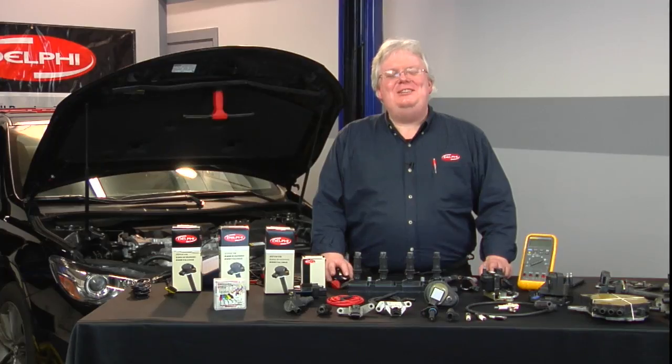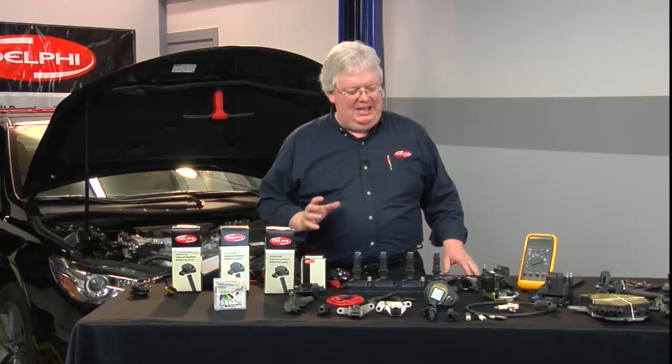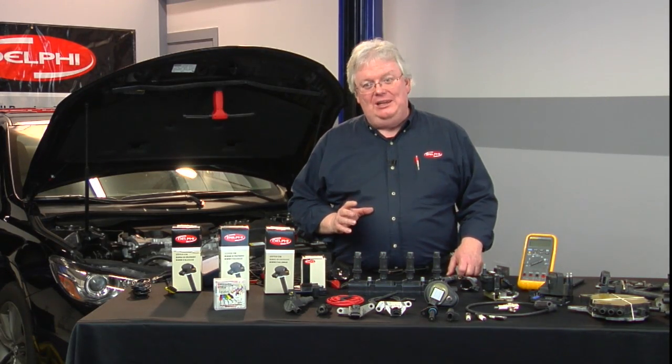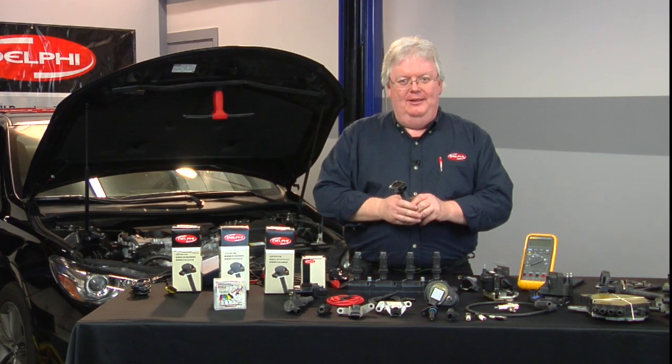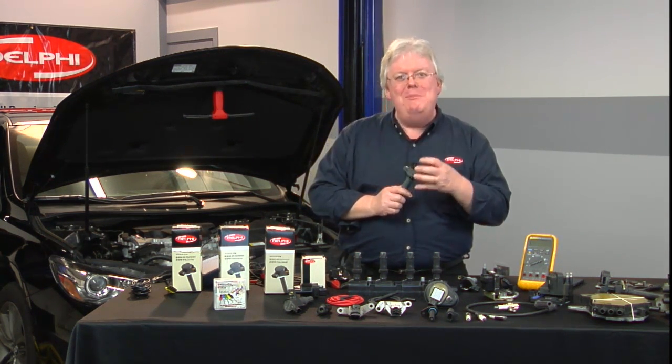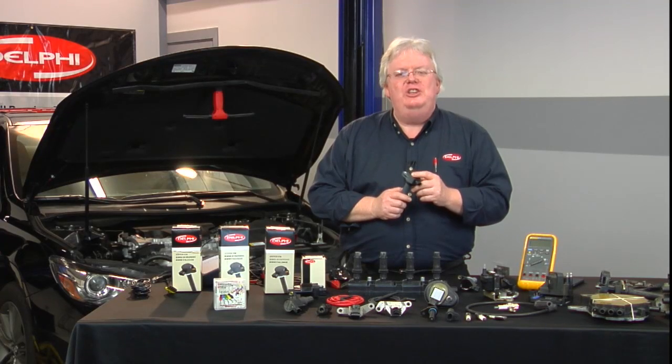All right, Dave, our numbers once again are in. We've got 36% saying B and 64% saying C. The 36th percentile have it. When you have an open circuit in the secondary, unless it's really a wide, huge gap of, let's say, half an inch or something of coil missing, it typically just burns through it. It jumps across it.